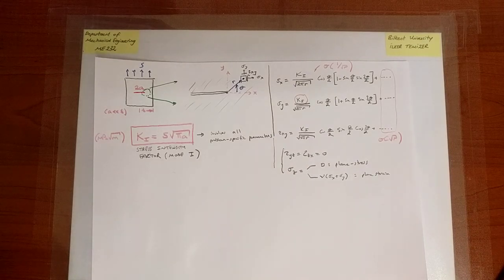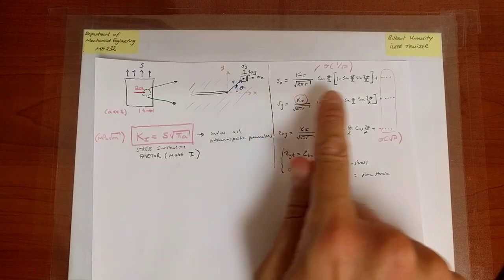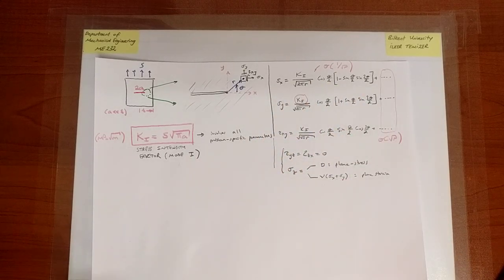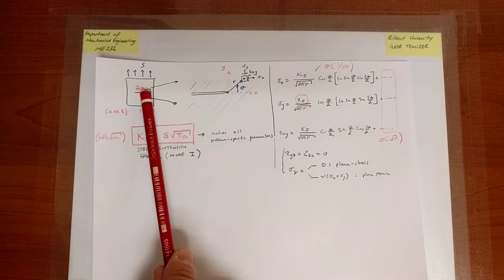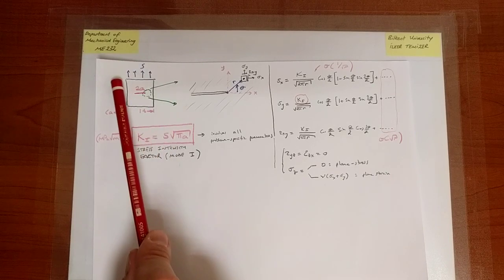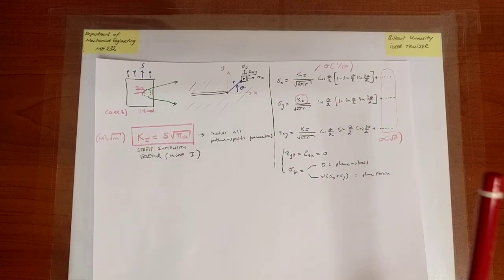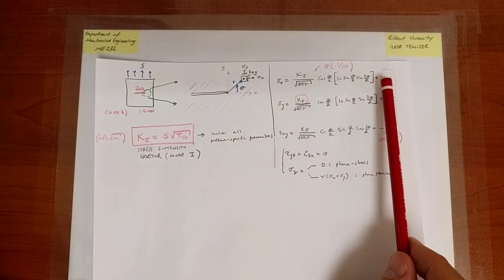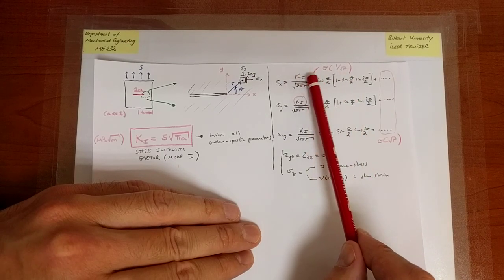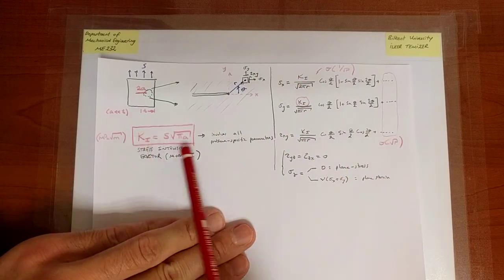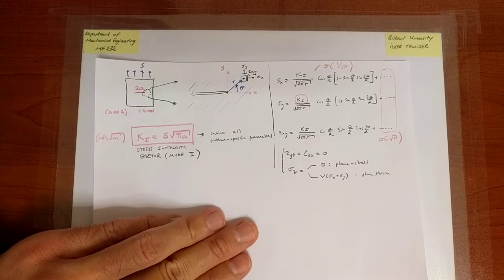All right, good. So we have our exposure to stress intensity factor mode 1, and we have stress fields that are described through that factor. We do not need to know these stress distributions. We don't need to understand where they come from. We just need to appreciate the fact that in the vicinity of the crack tip, despite the simple far field loading, the stress field is highly complicated. But that complication is mostly geometrical, right, through r and theta. All the problem-specific parameters are reflected in the simple parameter, the stress intensity factor, which we have to know by heart.